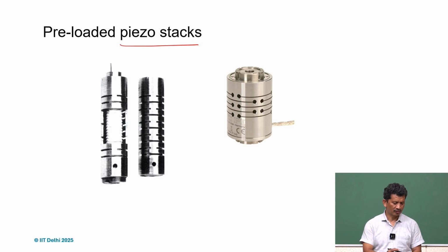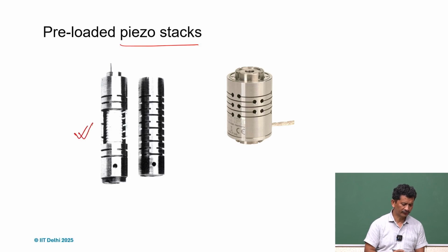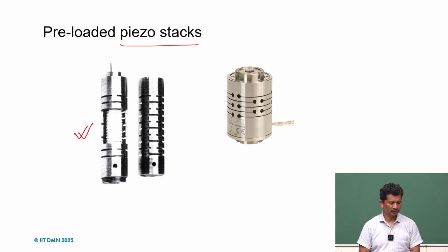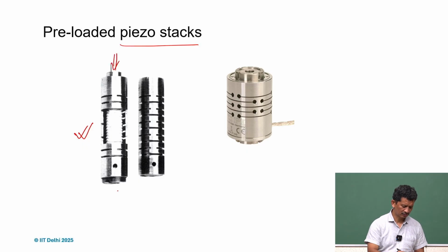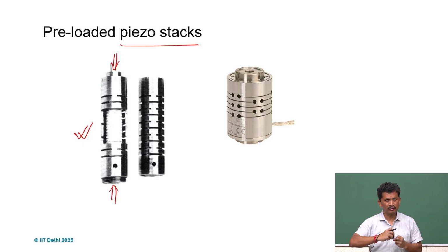So we can use this kind of arrangement, with alternate cuts, and the edge is chosen in such a way that when we tighten it from the ends, we can compress the tube and the tube gets extended and the material gets compressed inside. That is a very useful method in designing these kinds of actuators.